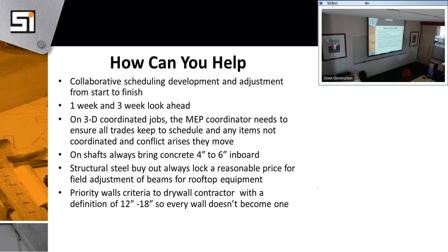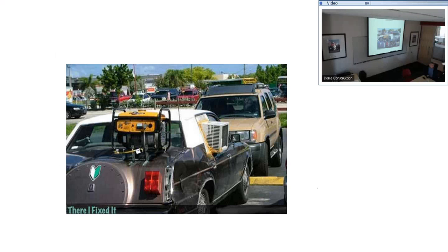So does everyone understand what a grade line is then? They're deceiving, because you look at a plan view of something, an MEP drawing or something, all the lines look the same. And what's the normal grading, by the way? A quarter inch, I didn't hear you. Quarter inch per foot. Yeah, quarter inch. Jurisdictions allow an eighth, but yeah, quarter inch is normal.